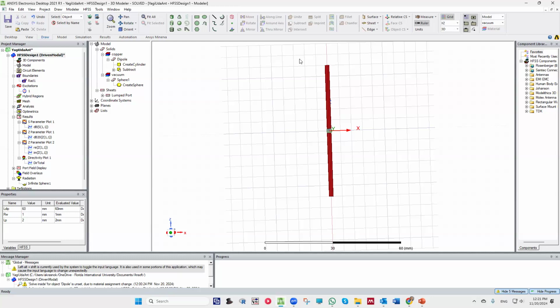And there's going to be another element called a reflector, put on the back. It's going to be a little bit longer than this active element, and its purpose is to destructively interfere and cancel the radiation that goes to the back.